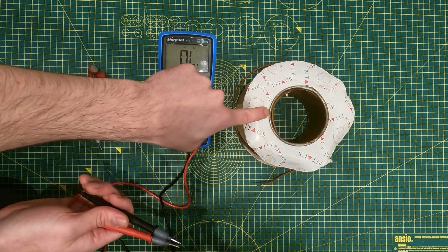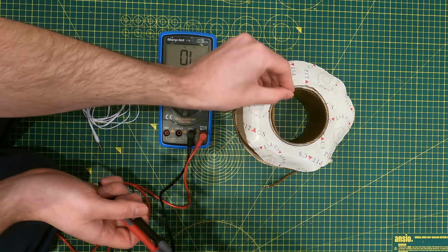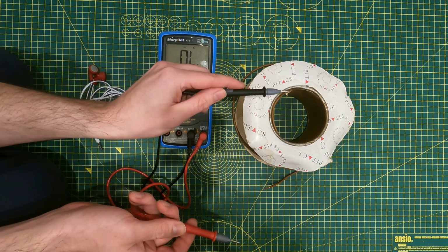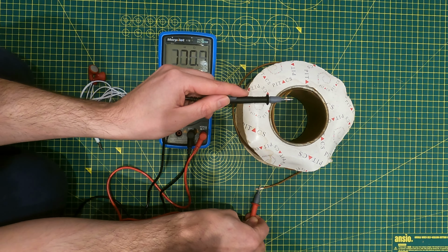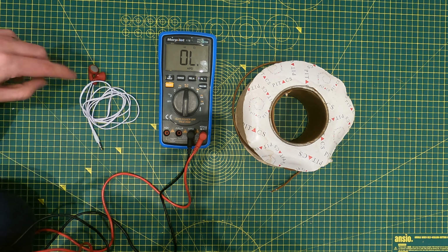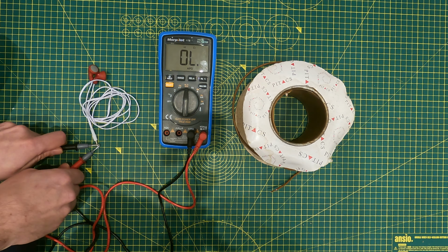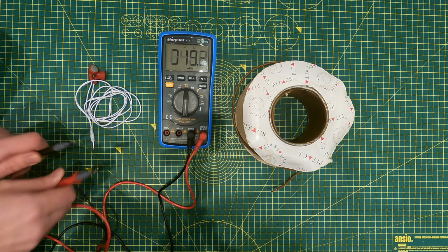So for example, I've got a reel of wire here. If I want to inspect the cable and make sure that it's complete with no breaks in it, you basically just get your test probes, put one on each end, and you get the audible tone. It's the same for these headphones. So say I want to make sure there's no breaks in the headphones. Again, you do the same thing, pop your probes on, and you should get an audible tone, like so.